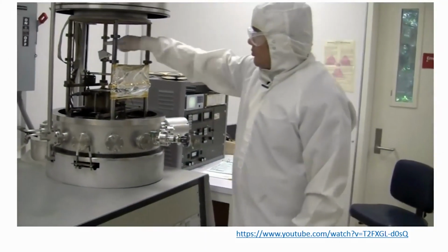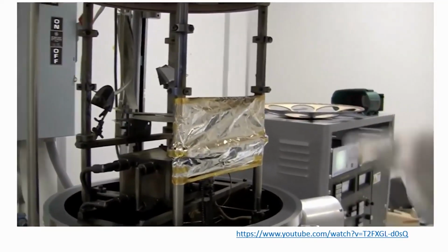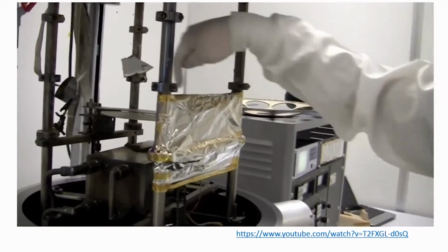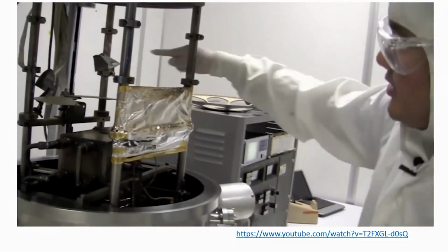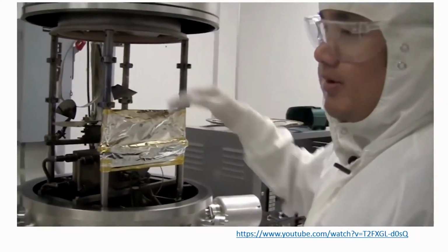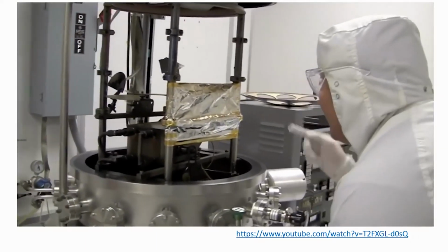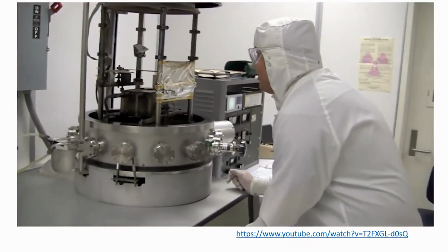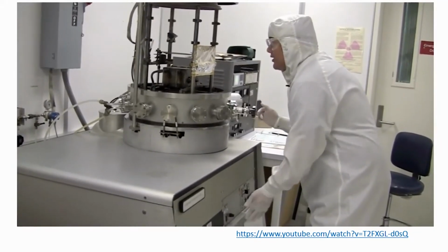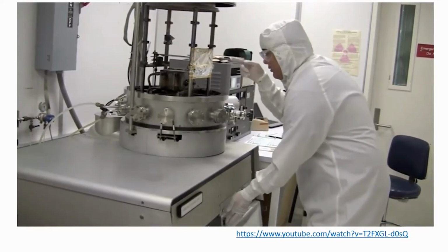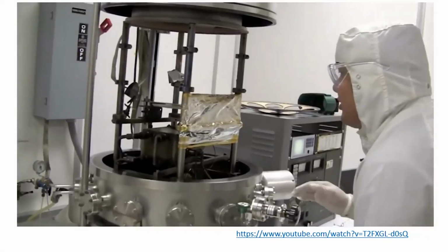It's also good to look at these 2 mirrors. These mirrors help you look at your crucible when you're depositing. This mirror lets you see your crucible when the shutter is closed. And this mirror lets you see the crucible when the shutter is open. So you put your head about this height to make sure you can see the mirror there when the shutter is open, and the mirror there of the crucible when the shutter is closed. I can see the crucible there when it's closed, and I can see the crucible there when it's open. So my mirrors are in the right position.